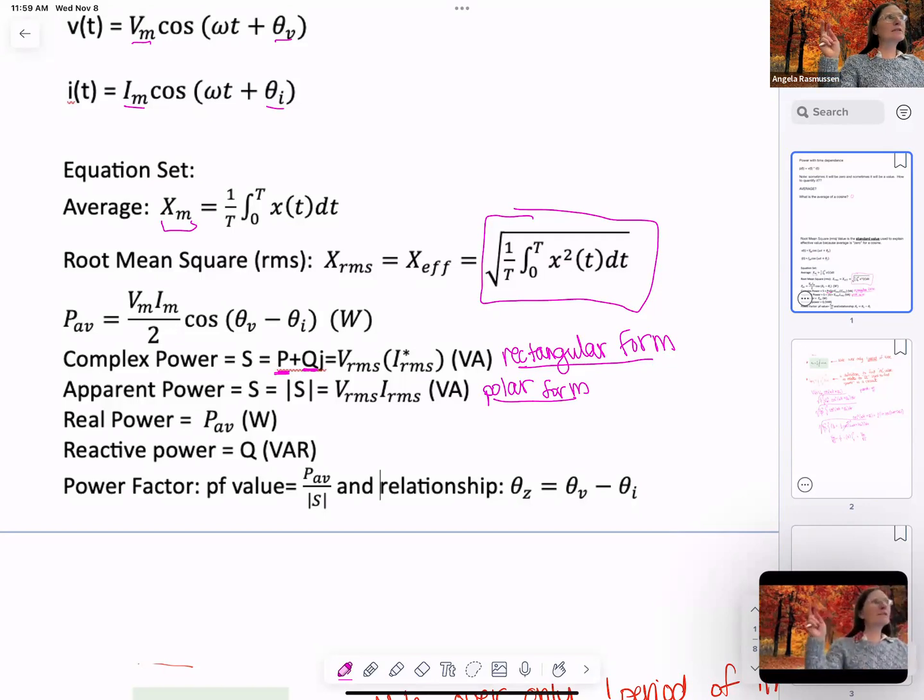It's still watts, power is watts, but volt ampere means an apparent power, and that also denotes that it's complex. So when you see volt ampere, you know it's talking about a complex power. VAR is volt ampere reactive, meaning just the imaginary part of the complex power. So they're all watts, but now we have two new terms to differentiate in the complex plane: complex power in VA, and the complex reactive portion, which is Q, in VAR.